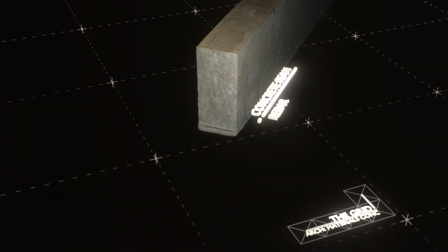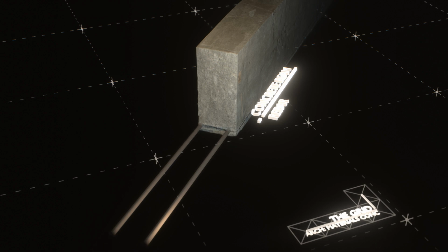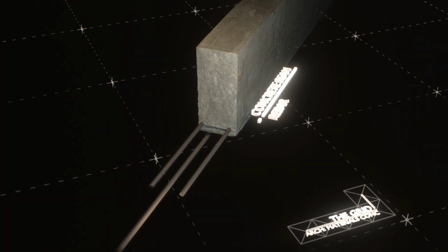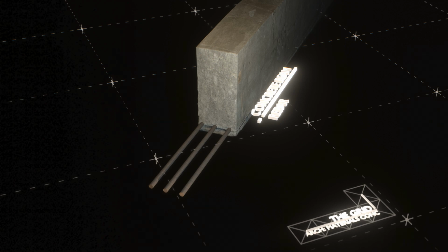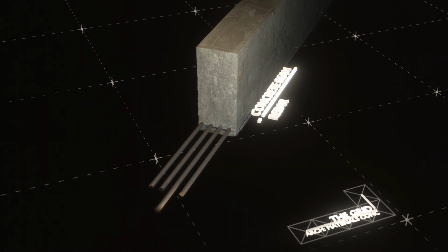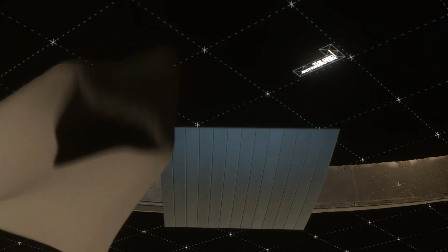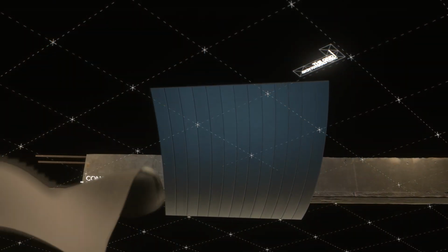So, generally for beams, rebar is concentrated at the bottom of a beam where tension is strongest. Perhaps even 3 rods are inserted rather than 2. Perhaps 4 might be required for a heavier job. 2 could be inserted at the top in instances where tension is on occasion reversed, like in an earthquake or hurricane, events where gravity causing tension is nullified and overtaken in power by even more wild outside forces. Allow me to become such a force and demonstrate.